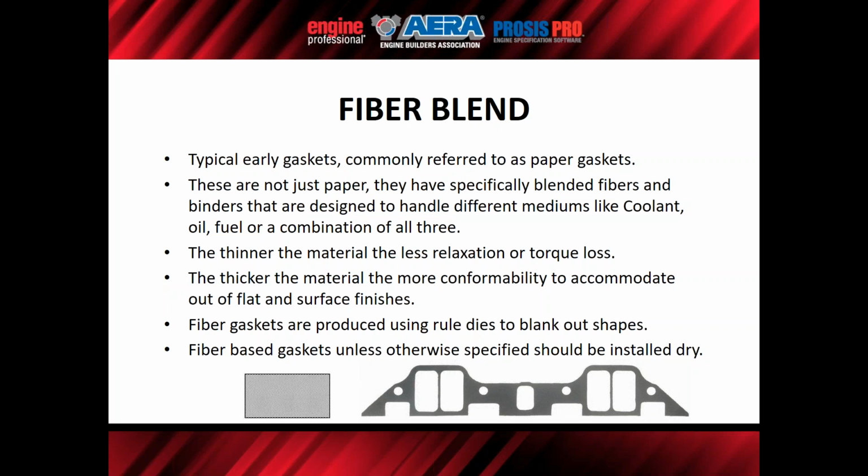So the fiber gaskets are usually produced with rule dies. So if you've ever seen a gasket operation, you'll see these rule dies being blanked on punch presses and blanking out shapes like you see down here. Like this, I believe, is a Chrysler 440. So all of these type of gaskets should be installed dry unless otherwise specified.